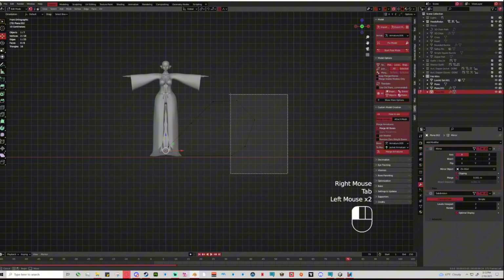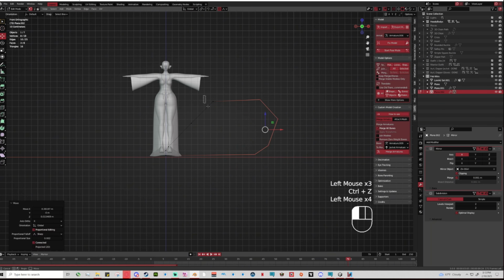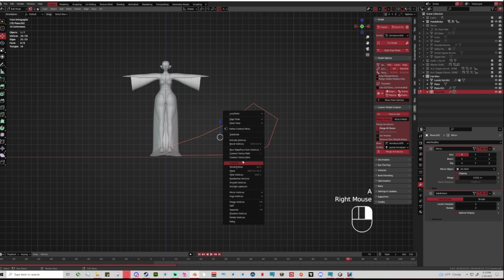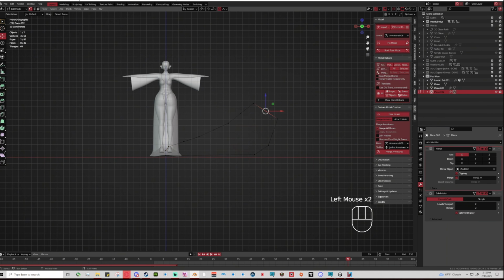And then you could go through and be like, okay, well actually, oops, I want this to be a little bit wider. I want this down. And then maybe you're like, oh, I absolutely hate it all. I want it to have more. You could select it all and do subdivide. And now you have extra points in between everything, and you can make it a little bit cleaner that way. Keeping in mind that you already have subdivision surface on it, so you don't want to subdivide it too crazy. That's going to make it super high poly.